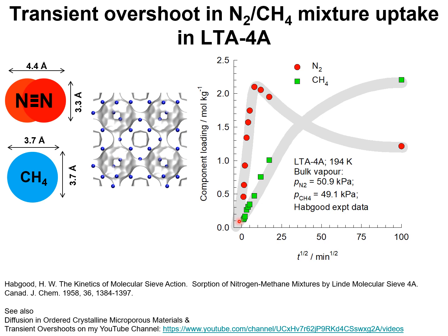In remote locations, pressure swing adsorption is used for the separation, and we need an adsorbent that selectively takes up nitrogen so that purified methane can be rejected and recovered in the gaseous phase. However, most known adsorbents selectively adsorb methane that has a significantly higher degree of polarizability than nitrogen.